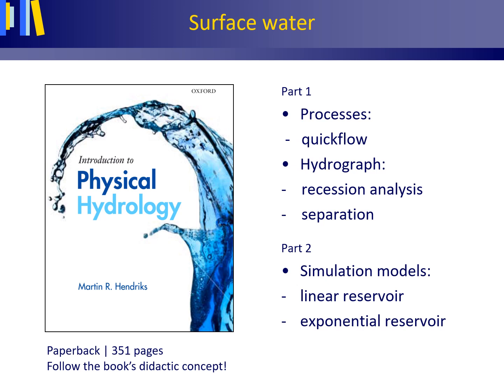In this lecture, we will discuss the drainage basin processes that deliver water rapidly to the stream, contributing to the so-called quick flow volume of a stream, discuss the hydrograph, which is a graph of the changes in discharge with time, analyze the falling limb of the hydrograph of a storm event, so-called recession analysis, and separate the hydrograph into quick flow and base flow, so-called hydrograph separation.